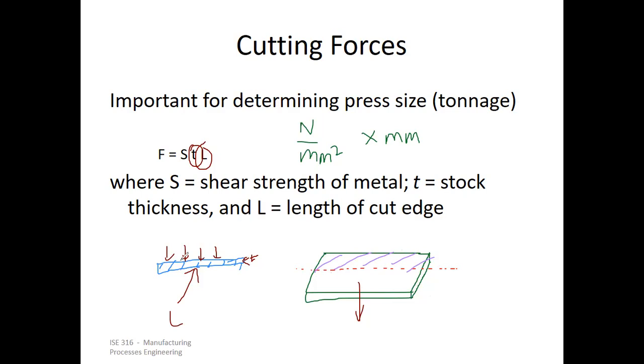And when the shearing happens, the area that resists is this thickness times L, the rectangular area. So that area is what is accounted here, right? So if that is the case, this is your geometrical factors, and this is your material factor. As for thickness, it is in mm, and as for your length, it is again mm. So if you maintain consistency of units, this would cancel, and therefore you will get newtons as the force.